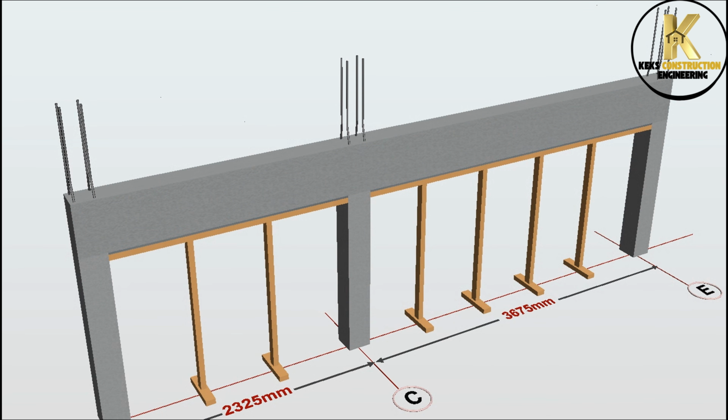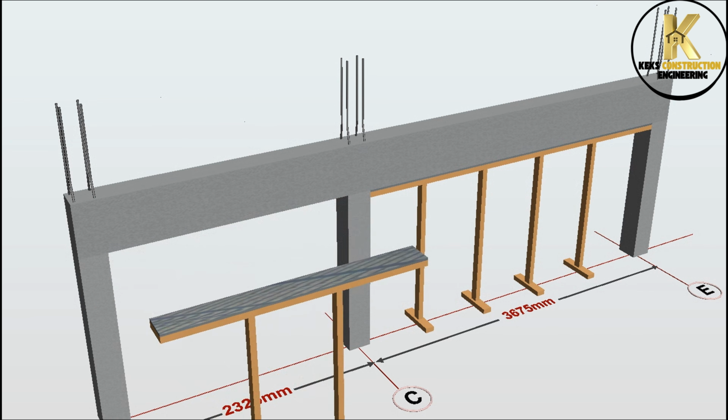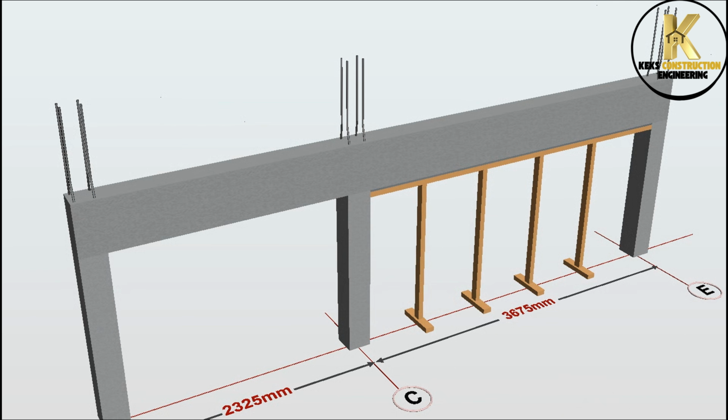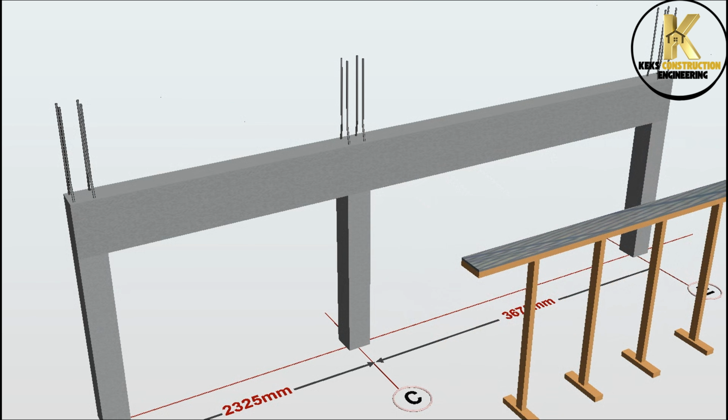Ensure the concrete beam has attained its maximum strength before removing the bottom formwork. Good job! We have completely read, interpreted, and executed Beam 01 detailed drawing.